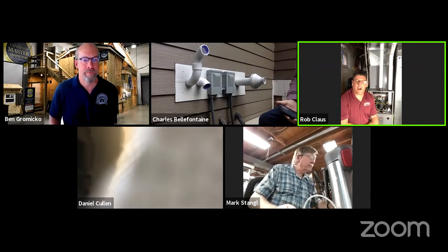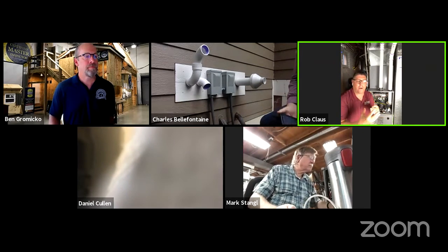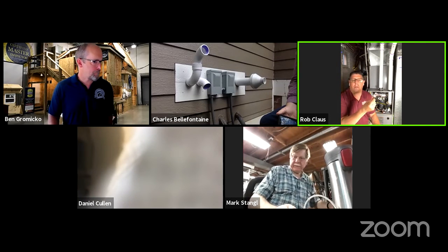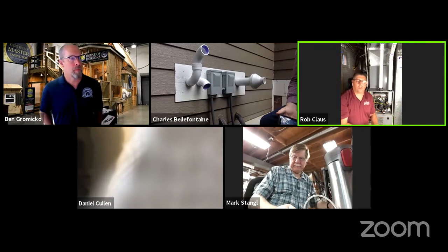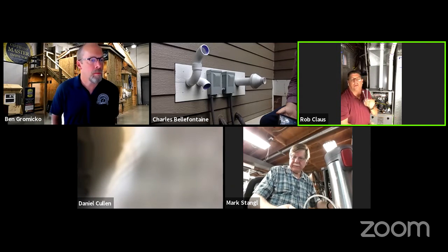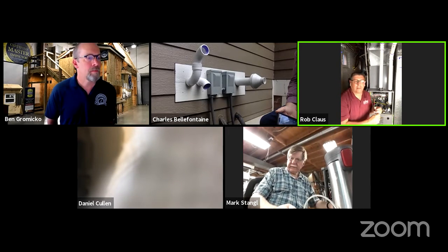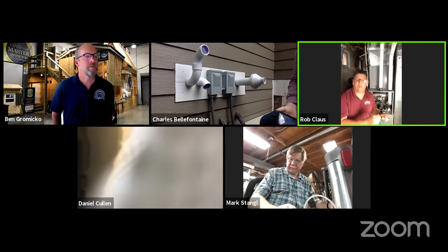And I wanted to summarize a little bit of that if I could, Ben, but I also want to add a couple of twists. One, Charlie talked about dial thermometers. Here at the Brick Kicker, we have offices all across the country. Everybody uses dial thermometers for furnaces. It's a simple delta check. Every furnace has got a portal.